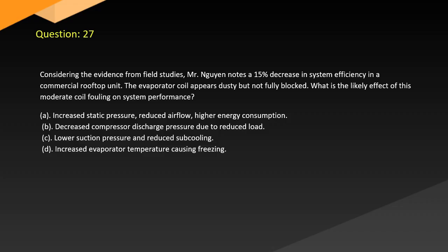A. Increased static pressure, reduced airflow, higher energy consumption. B. Decreased compressor discharge pressure due to reduced load. C. Lower suction pressure and reduced subcooling. D. Increased evaporator temperature causing freezing.